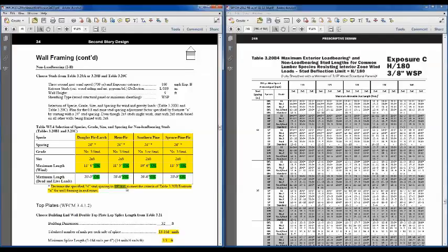So whether your part of the country realizes it or not, that is an ASCE 7 provision. Those end zones do have higher wind loads, and when we redo these tables, we could take the most conservative approach and incorporate that 0.8 factor from the beginning, and then allow you to back that out.